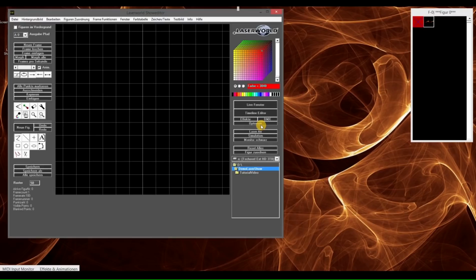This is the line that we want to have fade in, fade out. To do that, we select the multi-line tool and the white color. And the multi-line tool has the feature that if you left click, it draws a visible point, and if you right click, it draws a non-visible, a blank point. This is an important thing because blank points and visible points have different behavior when it comes to fading.